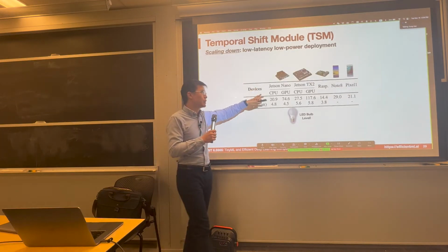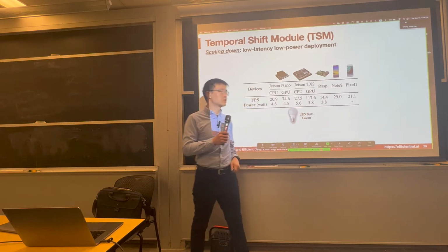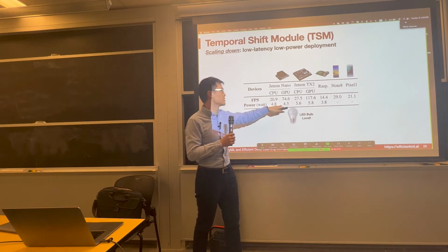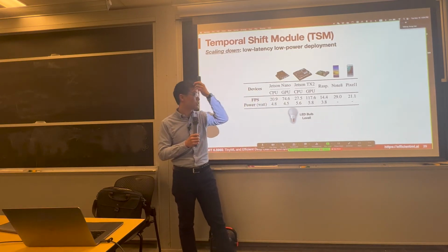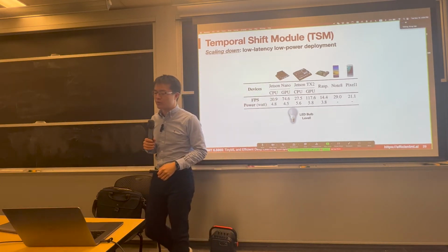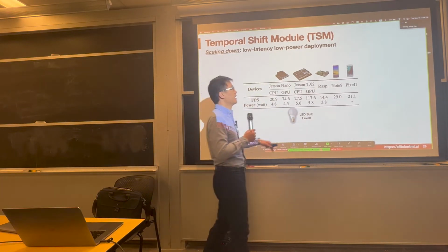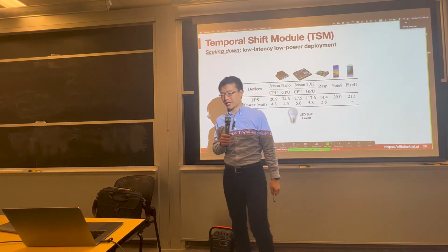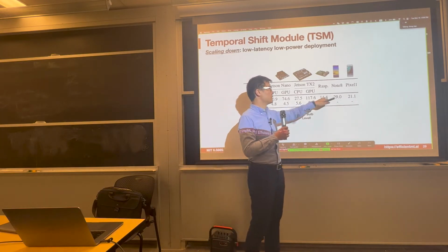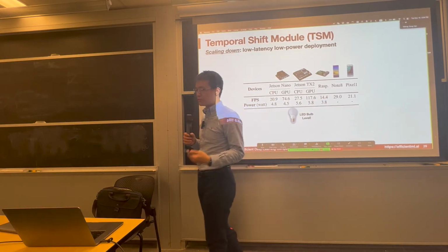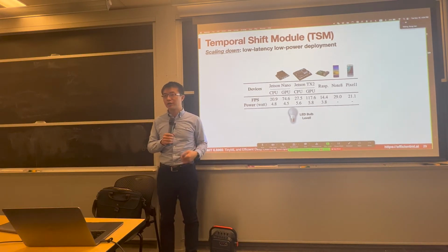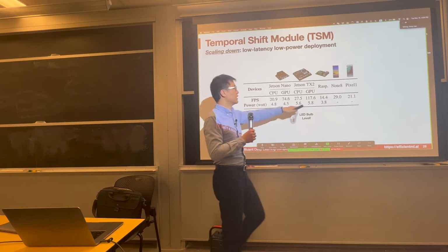Temporal shift module is pretty energy efficient. Actually, we can use LED bulb level of power, just a few watts, 4 watts, 5 watts, on just a Nano. On the GPU, we can perform 74 frames per second. Even on the Raspberry Pi, at that time, we could perform 14 frames per second. And recently, after our kernel optimization, we can accelerate this to 30 frames per second on the Raspberry Pi using the MobileNetV2 backbone, okay? Which can enable a lot of gadgets to understand video.